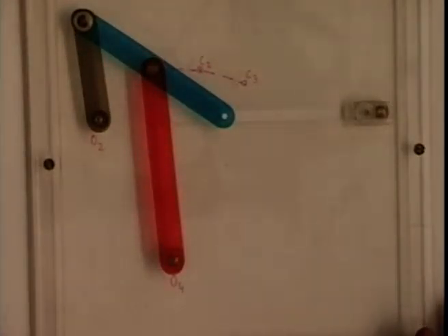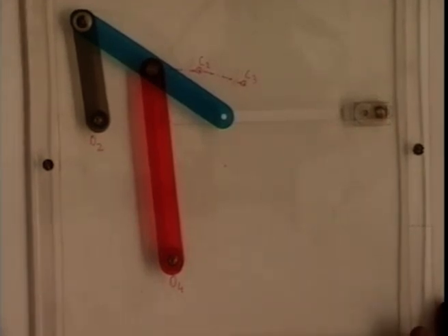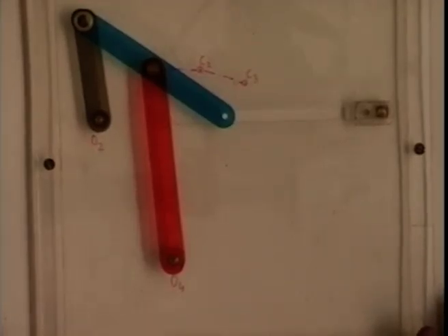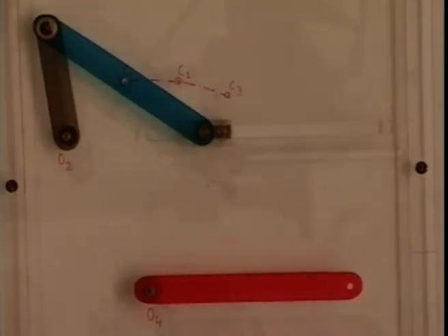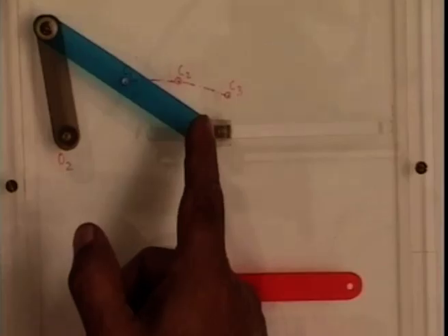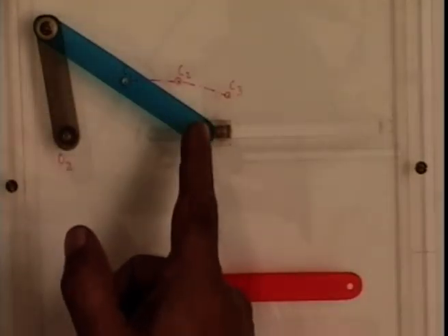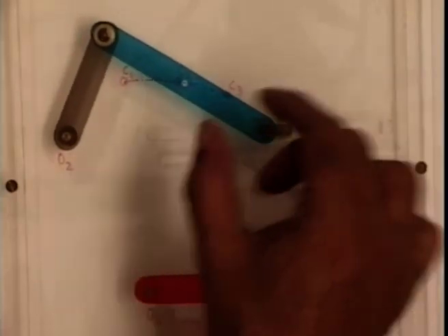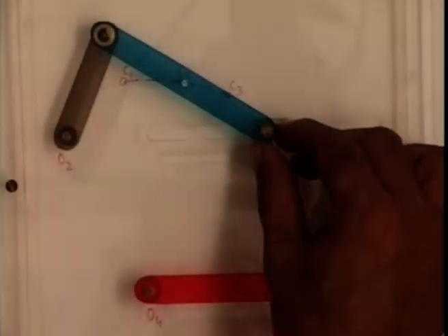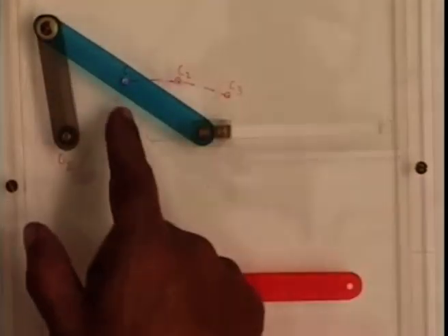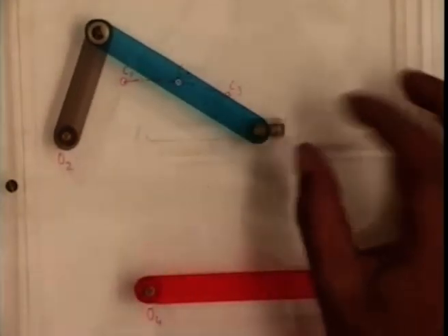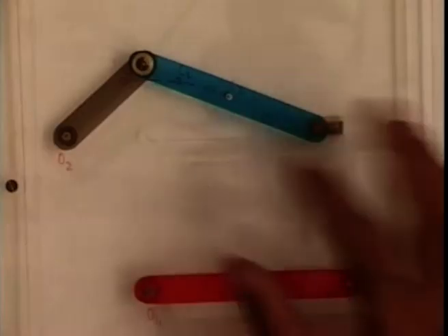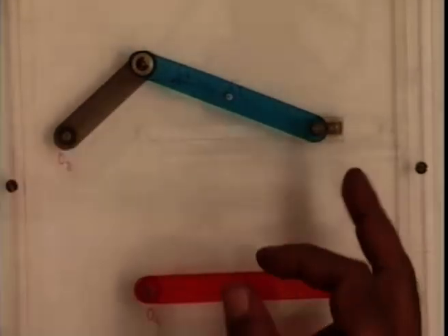So all the methods that have been taught so far can be cleverly used to design more complicated mechanisms, rather mechanisms with more complicated motion requirements. Let me now repeat this two-stage synthesis problem. First we designed a slider crank mechanism such that it acted as a function generator. The slider displacement was coordinated with the crank rotation. Then we took the midpoint of this connecting rod at these three configurations, which is C1, C2 and C3, for the three positions which have been generated by this slider crank as a function generator.